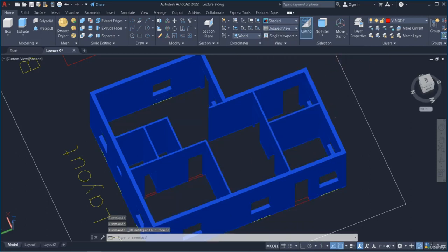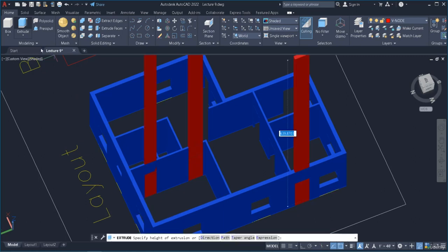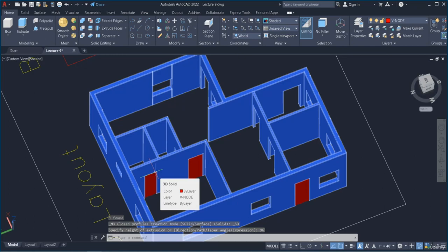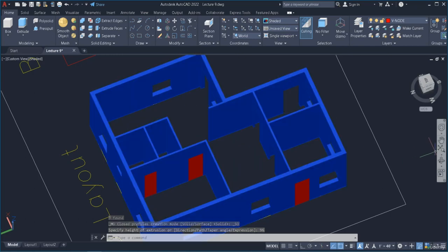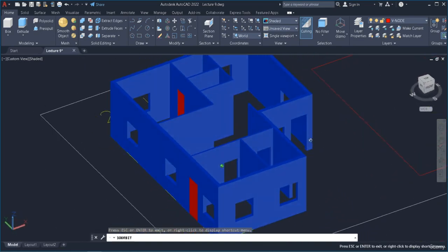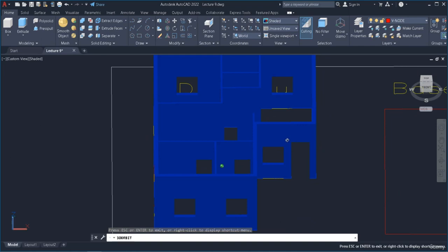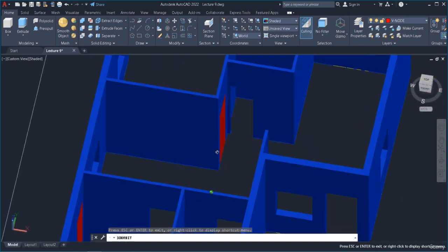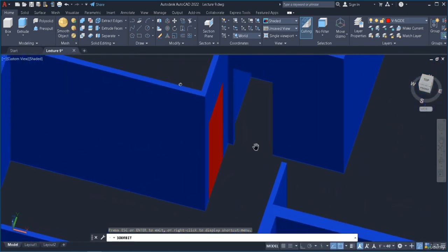As you can see, I'm not going to use rectangle or write RECT again and again. Let's isolate and hide the base so we can easily view it. So these are the three doors created. We can use the extrude command, extrude them up till this point. They are approximately 8 feet in height. These are the simplest format for the doors. That is just creating a rectangle, giving a starting and ending point, and then extruding it to the relative height.